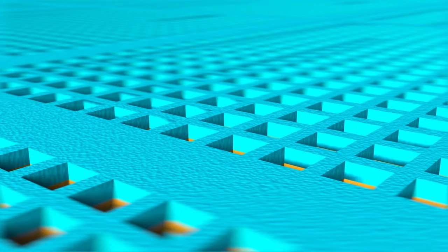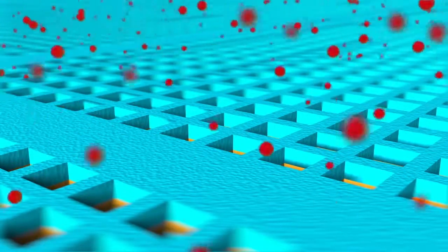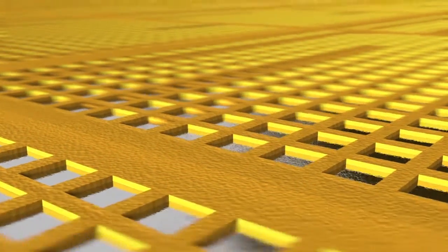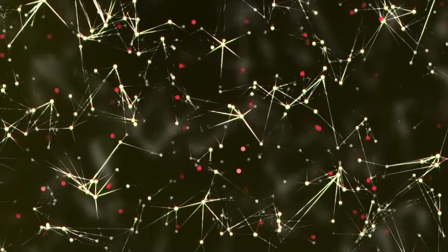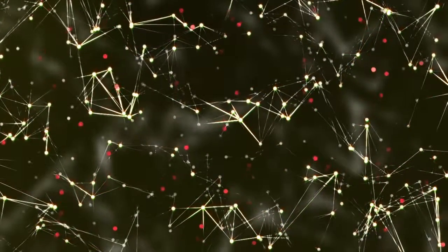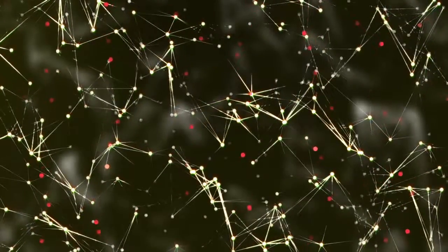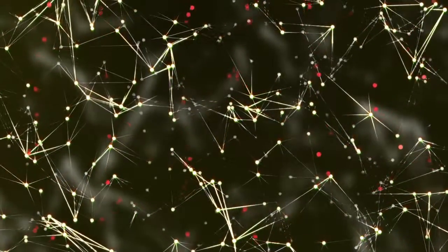The silicon regions are treated with either N or P-type doping through ion implantation. This example is one of an N-type doping. The photoresist can finally be removed. Looking at the doped regions, it can be seen that the implanted electrons are able to move freely and thus are able to carry electrical current.